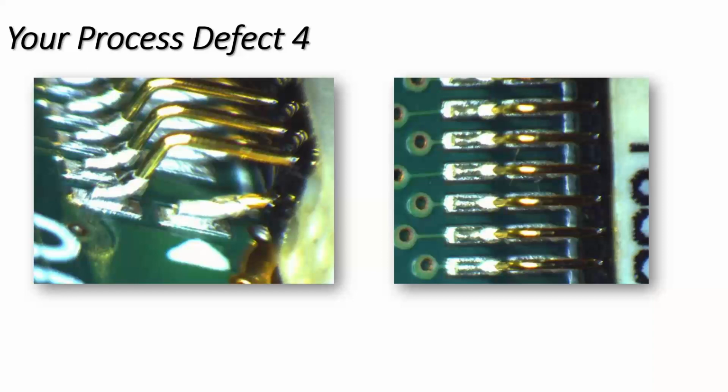If you look at most profiles on reflow soldering systems, if you look along the sort of 6 or 8 or 10 zones, it's 120, 150, 180, 240, 260. And those temperature set points are mirrored. So below, for the bottom heaters, they're the same. But they don't have to be.